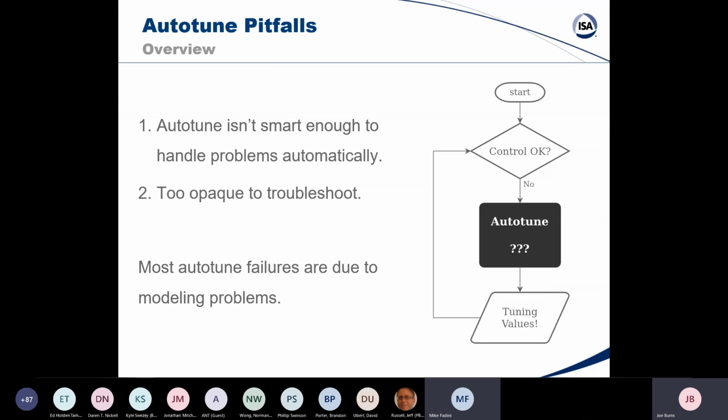Okay, I also have another one: when using electric actuated final control devices, is there a duty rating entry available to maximize motor life, a way that it doesn't work so hard? That's going to depend on the final control element that you're using. That's not built into the software, and that's going to be a judgment call for the user who's tuning, whether they can tolerate higher pump speed or not. Thank you. Yep.